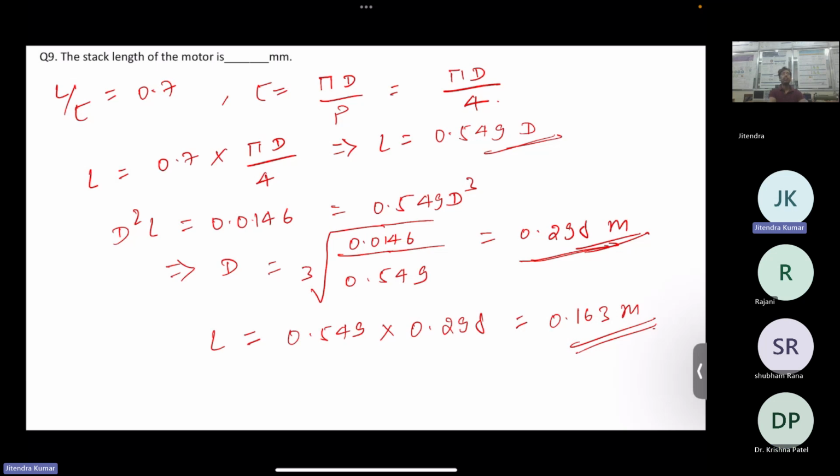Peripheral speed and flux density, there is no direct relation between them, because in air gap flux density or magnetic loading, what matters is how you have distributed your magnet or field winding, right? Even in the torque equation, which is a factor of magnetic loading, there will not be any speed. So there is no relation. I don't know from where you are getting this question.